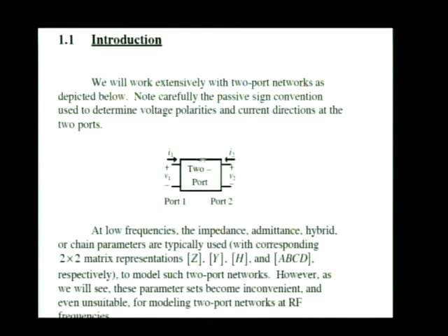That's our two-port. It has terminals, two of them, on port 1, which is the port over on this side. I sometimes call that the input port. And here are the terminals on port 2, which I sometimes call the output port. I really shouldn't use the terms input and output for those two ports because you could just as easily hook a source up over here and a load up over there on port 1. It doesn't really matter which you use as input or output.